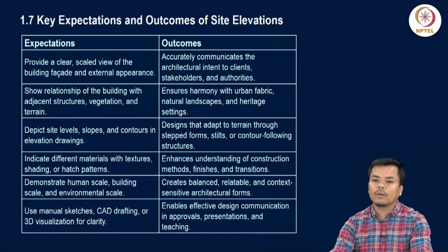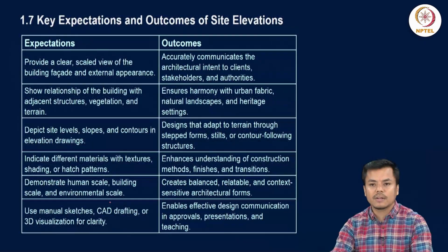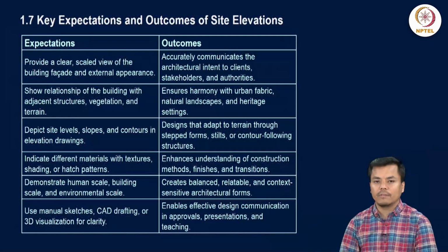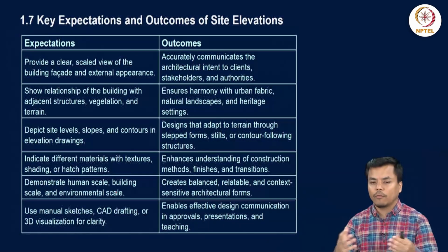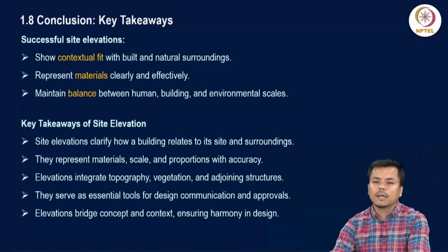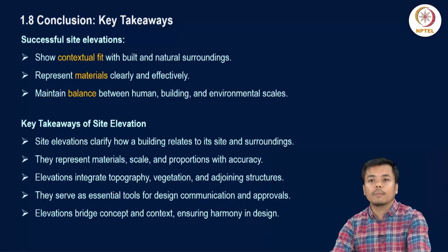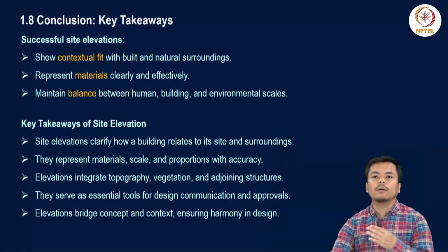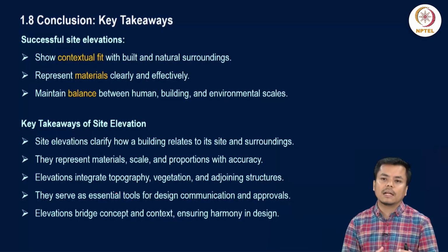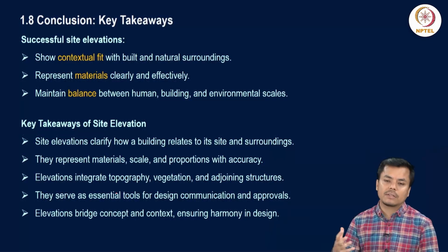You can use manual sketches at a very preliminary stage, then you finalize it by drafting, and at a later stage you can use this site elevation for the 3D view or 3D modeling of the entire structure. Then to conclude this presentation, a successful site elevation should showcase the contextual fit with built and natural surroundings. It should represent the materials very clearly and effectively, and maintain the balance between human, building and environmental scale. So the key takeaway is that site elevation should clarify how a building relates to its site and surroundings.